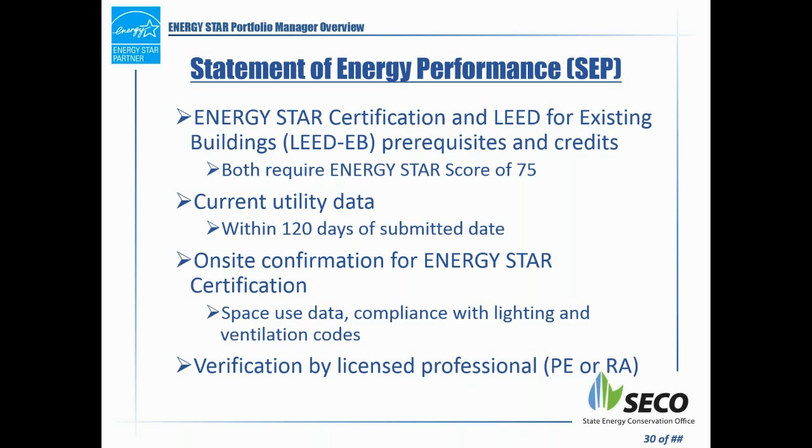This does usually require on-site confirmation for the Energy Star certification, just to verify the space use data. Like, is this really an office space, or is it really the warehouse? Like you saw those building types earlier. Make sure everything's in compliance with the lighting and ventilation codes. This does require the verification by a licensed professional. Some different programs, like the SECO Schools and Energy program, can also help with that. There's other places you can also get a professional engineer to do that.